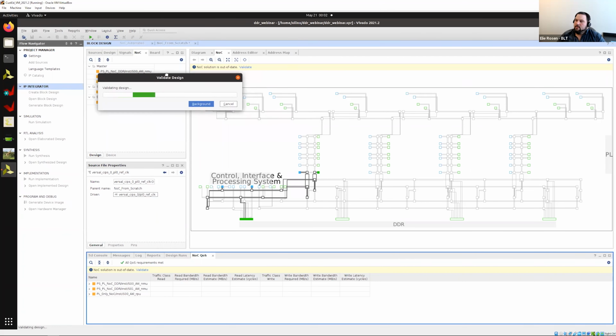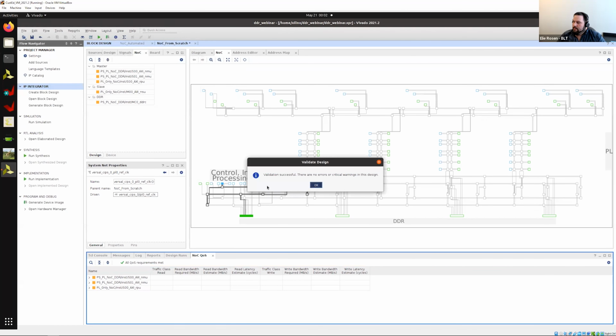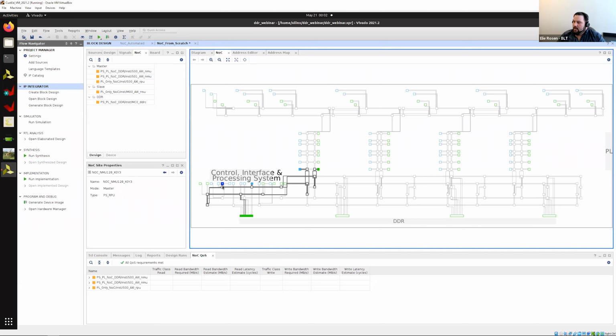And so now we can see that we have a NoC interface here where we're using the low power domain NoC interconnect, and that's what's traveling through this interconnect, going all the way to this NoC slave unit, because in this case the SIPs is talking to the block RAM, AXI block RAM controller. And then here we have the NoC master unit, which is talking to the AXI traffic generator, as well as this master unit that is going to the DDR controller.